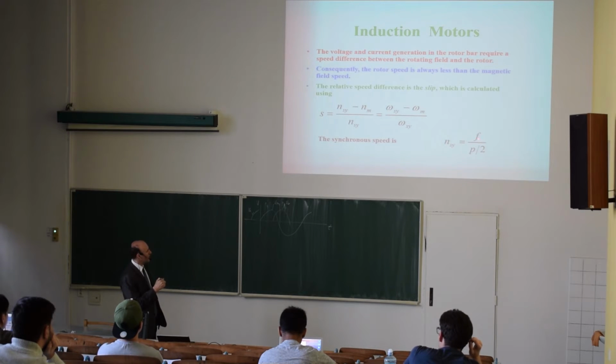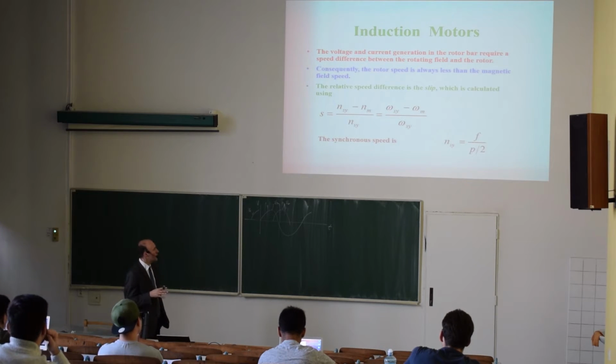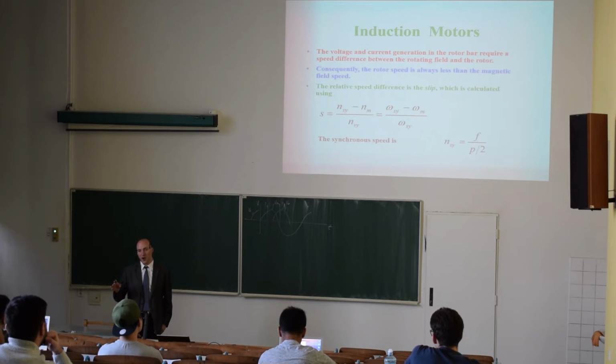So this will be one way how we could change the speed of an induction motor. We could have more windings and we could switch them in operation, but stepwise. We can switch between one pole pair, two pole pairs, then probably 3, but it will be a very complicated construction. But the easiest way to control the speed of an induction motor will be to change the frequency of the power supply voltage. And this will require a frequency inverter, which we will cover in about 2 weeks.